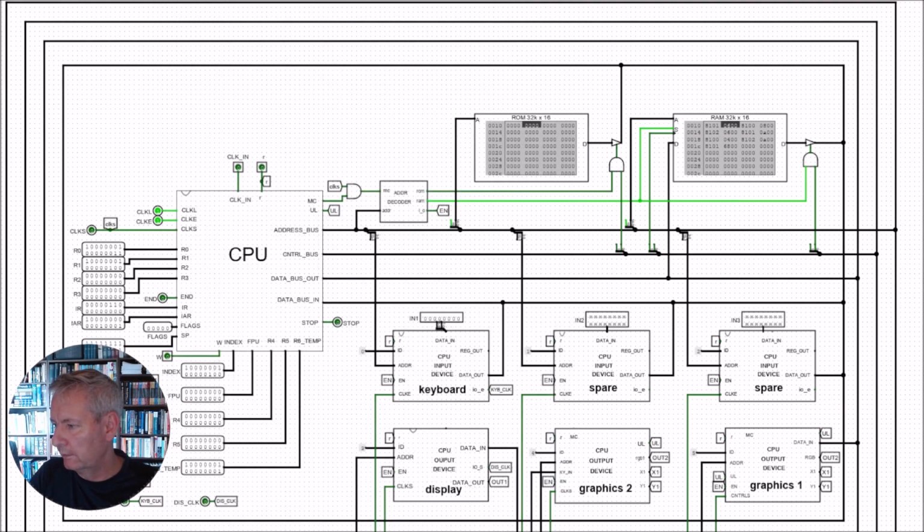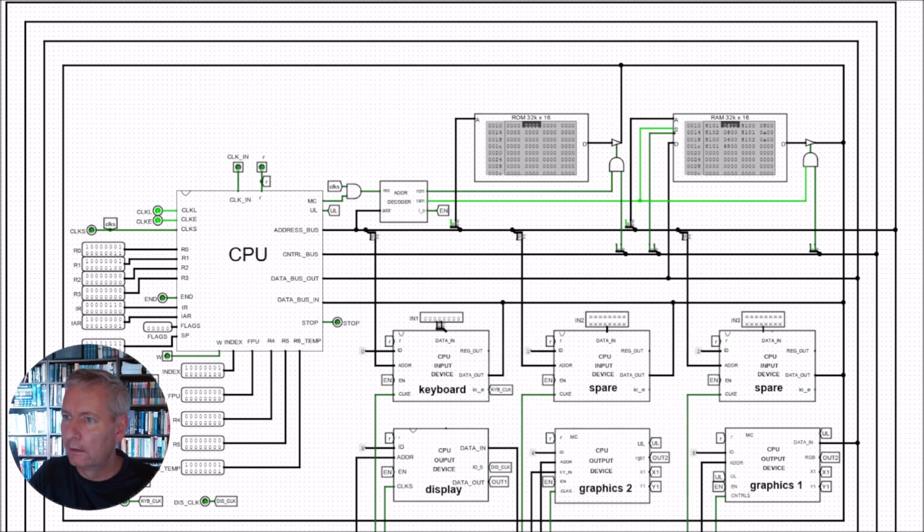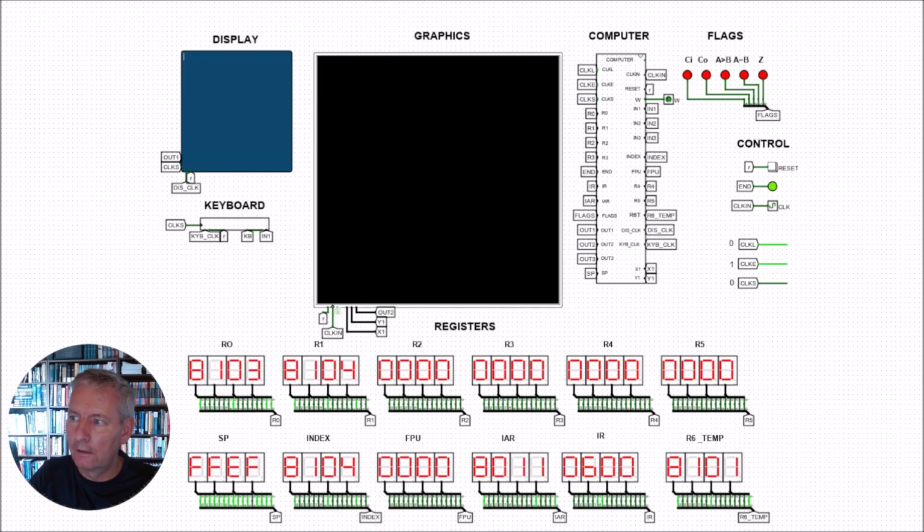Now if we continue, you'll see that we're going to take the number 10 and it's going to get into register R0, and then we'll put it into the temp. So we'll go ahead and do that now. So we should see the value 10 get into register R0. So that's the value 10, which is A. And then we have to take that value and we have to put it in the temp memory location.